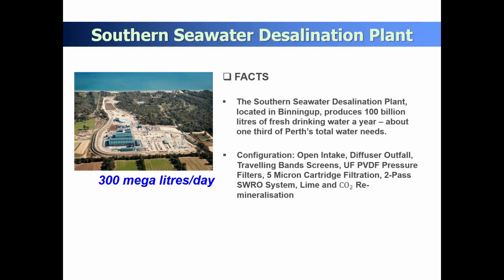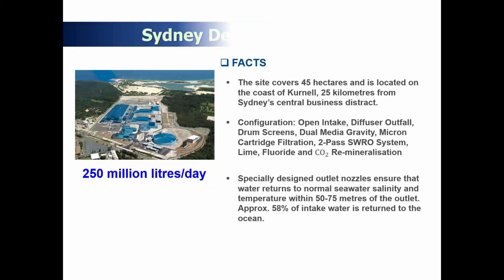So you can utilize ultrafiltration as a treatment for the reverse osmosis process. Depending on your confidence or your knowledge, you can decide in your assignment ultrafiltration as a treatment or media filter. That's the major difference in your assignment 3. If you design this way, your design parameters will change. If you go for ultrafiltration, you have to go for a different design process. So it's up to you.